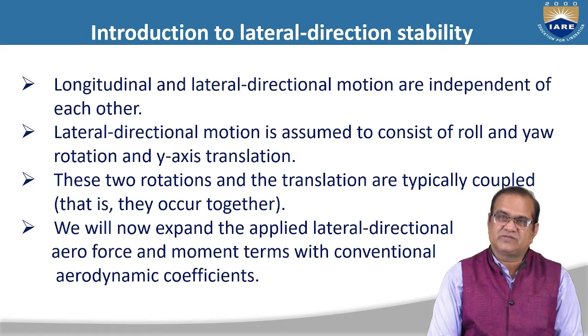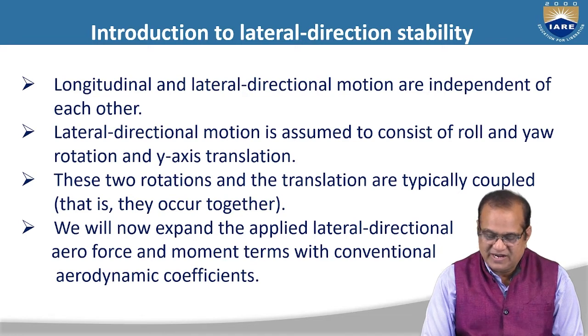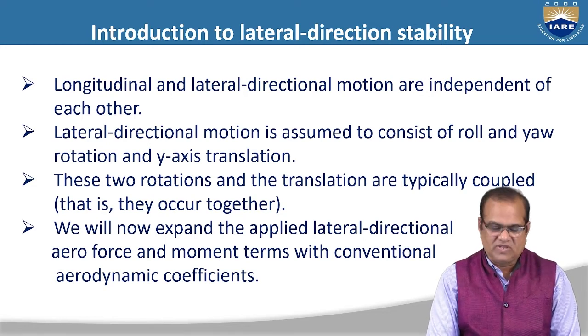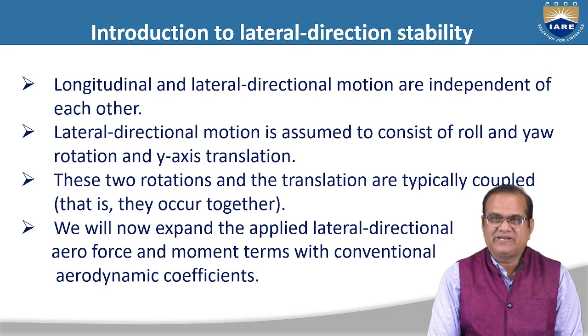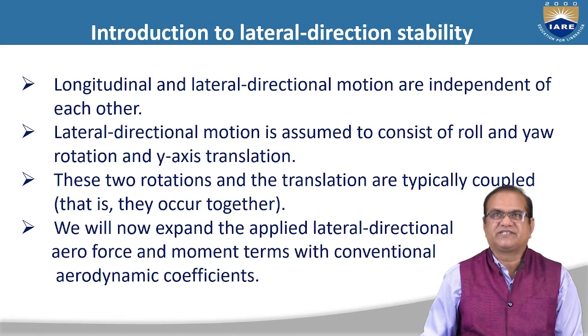Just now I have explained the roll and yaw. Both are coupled. If you roll, a yaw will be there. If you yaw, roll will be there. You cannot make them different. We will now expand the applied lateral directional aero forces and moment terms with conventional aerodynamic coefficients.